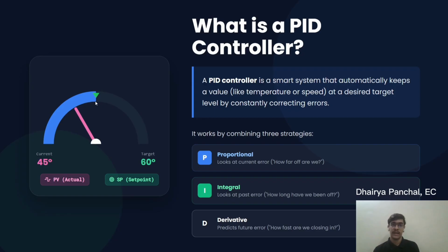This is called an on-off system, which we'll discuss in further parts of this session. It uses something called an on-off controller. That means you have a baseline value of 22 degrees Celsius. Your air conditioner runs till your system reaches 22 degrees Celsius, then it goes below 22 degrees Celsius. After crossing your set point value, your system will turn off. So now the temperature is, let's say, 20 degrees Celsius, and your air conditioner is off. It will let the value reach 22 degrees Celsius once again.